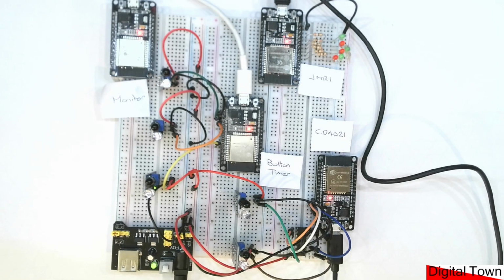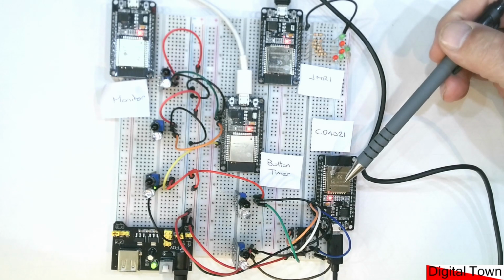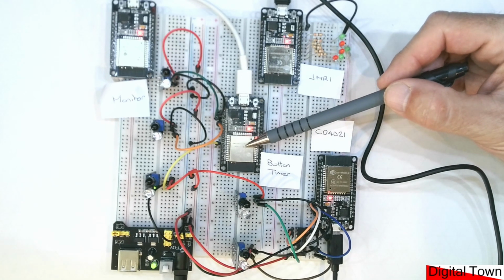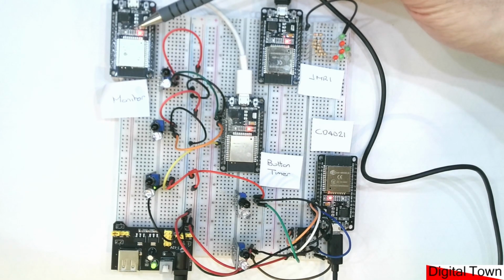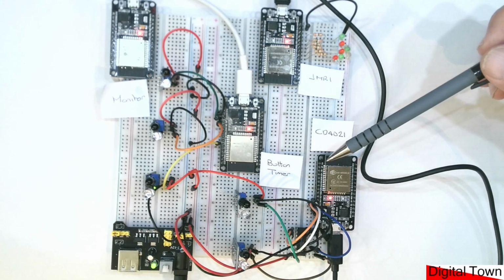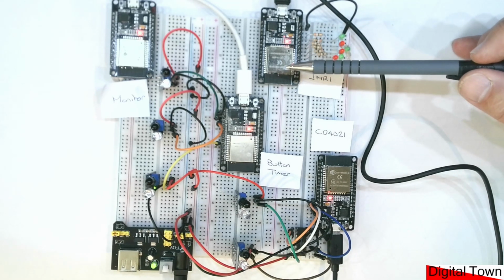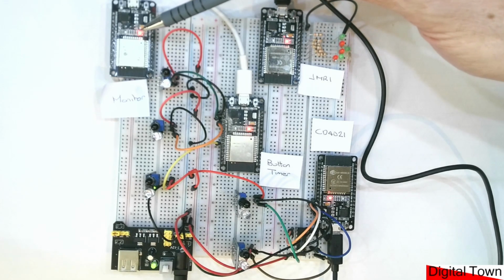So the setup for today on the webcam, JMRI is running on this ESP32. I've got some sensors running through a shift register on this particular ESP32. I've got another set of sensors on this center ESP32, and this ESP32 is acting as a system monitor because not only am I sending sensor data to JMRI, but JMRI is also sending turnout commands and light commands into nowRail. So I will be able to see those on the monitor over here.